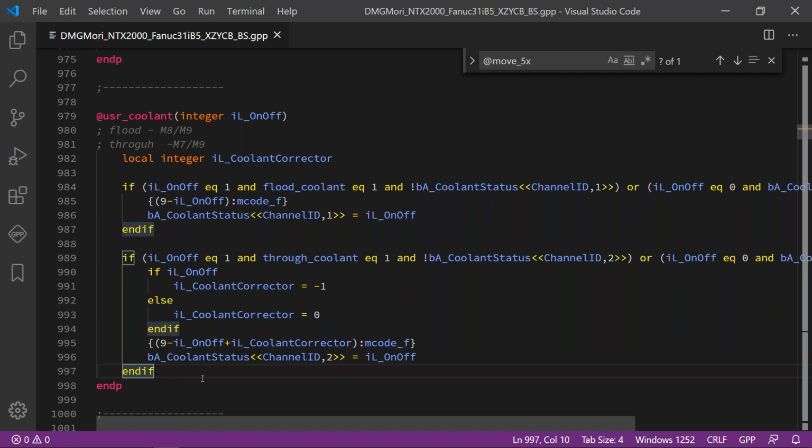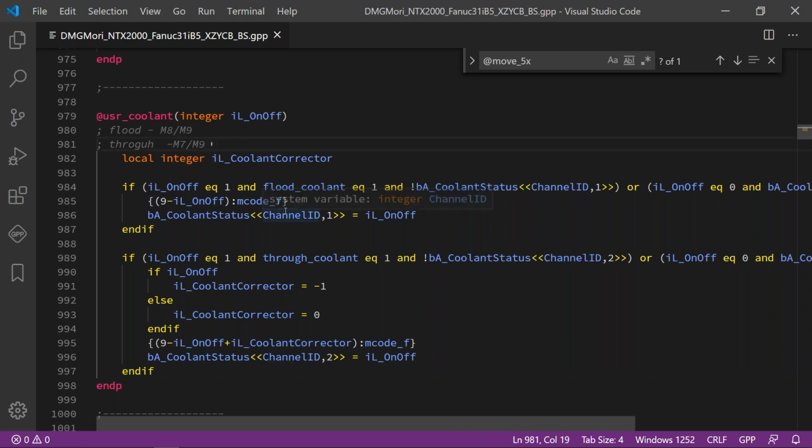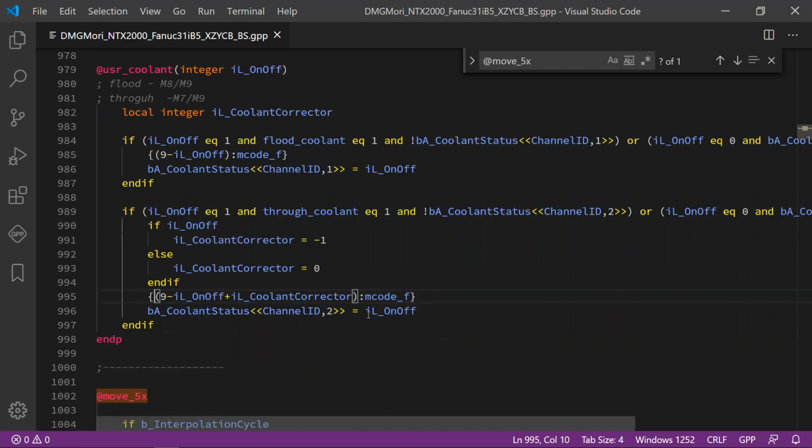This condition can also be improved more. If one M9 is called, then turn off the status of the others. Some controllers can have only 4 M codes in one line, so you can basically, guys, create a new block after the 4th M code or coolant. So this is something that I don't want to show you here.